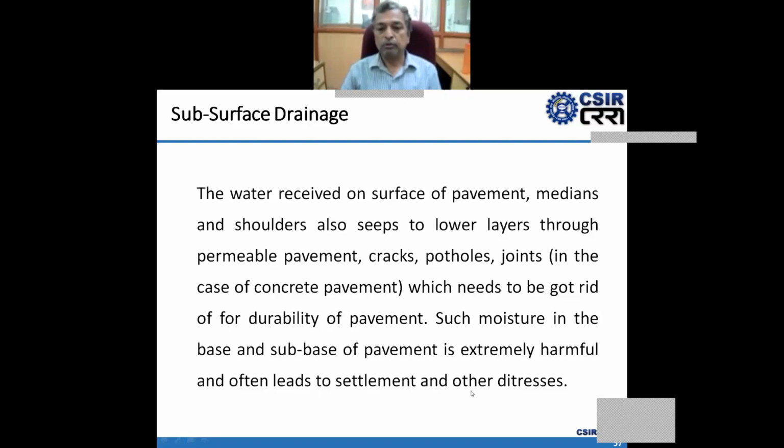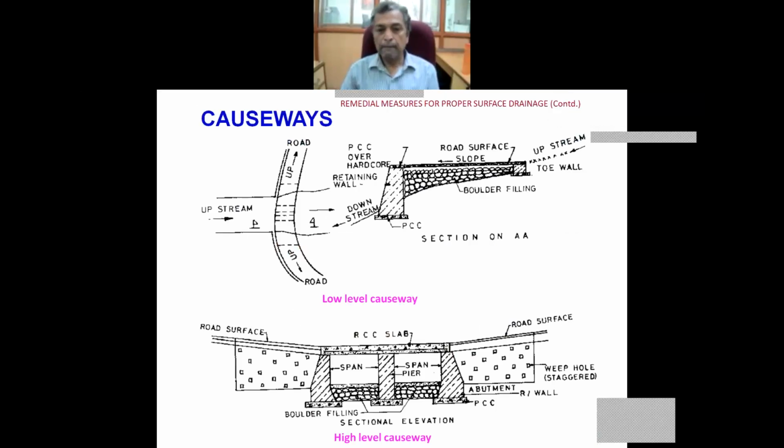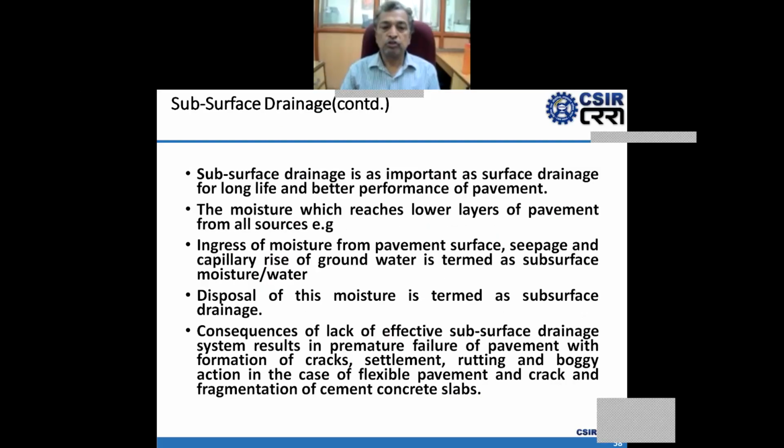So now we will discuss here. Subsurface drainage is as important as surface drainage for long life and better performance of the pavement. Moisture which reaches the lower layers of the pavement from all sources, ingress of moisture from the pavement surface, seepage, and capillary rise of groundwater, is termed as subsurface drainage.